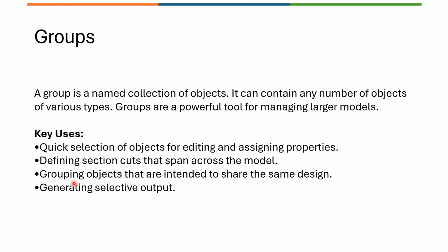And the important thing here in the steel building would be the intent to share the same design. For example, if you have a particular floor level where you have an auto select list, the program would have optimized, then each member can be slightly different from the other. Then we can group them and ask the program to consider the largest one for all members in that group. So this one will be greatly helpful. It will be more practical in the steel design during optimization, and it will also be used in getting the outputs.